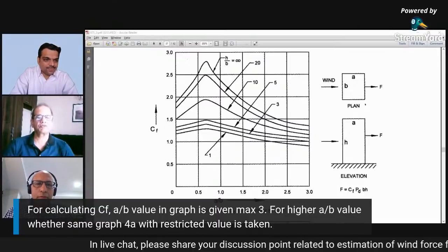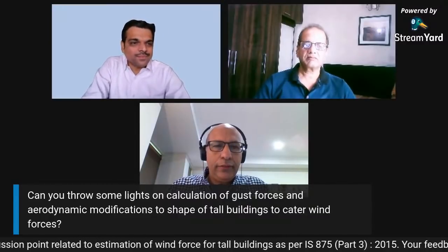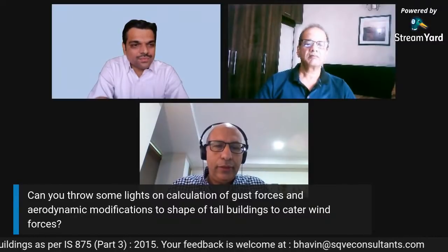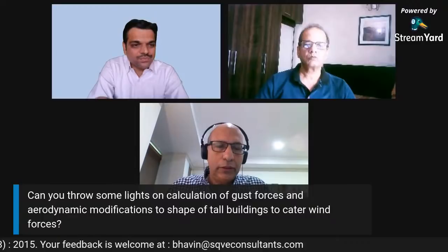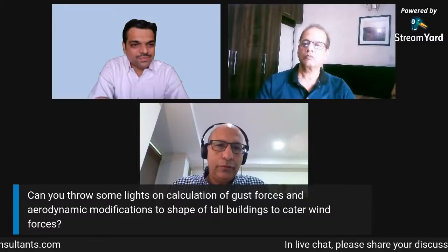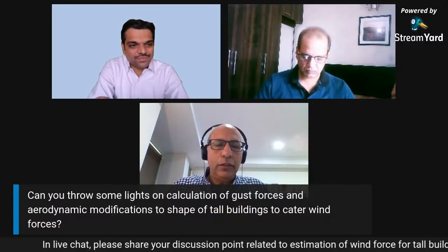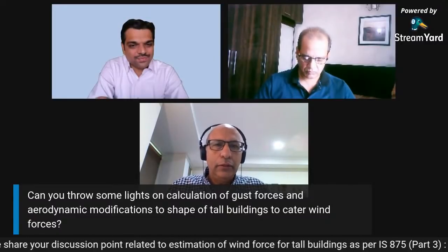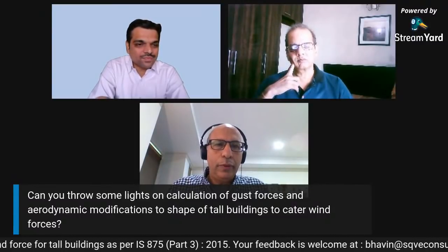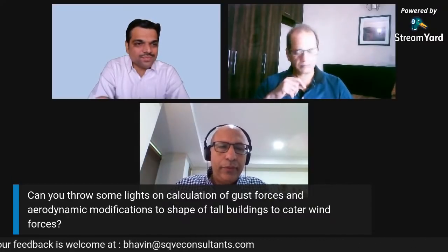Yes. Right. Just be careful with torsion though. As a rule of thumb, you may want to refer to the ASCE or the Australian AS 1170.2 for guidance on torsion. In both of these standards, the torsion is a function of the along-wind response, and it's generated by offsetting the along-wind point forces by anywhere between 0.15 to 0.2 of the width of the building. And you'd offset, obviously, in either direction to see the effect of that.